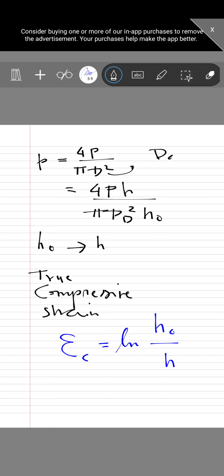Now as the strain rate increases to 10 per second, servo control testing machines can be modified to maintain the constant true strain rate. Now for metalworking, strain rates range from 1 to 10 to the power 3 per second.